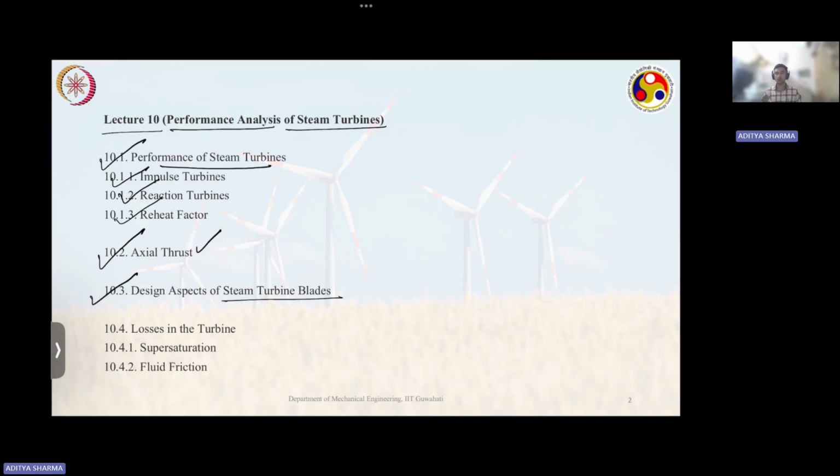But if you see the whole blade from the axis of rotation, omega is the same for the whole blade, but the radius changes as we move towards the tip of the blade, which eventually changes the blade velocity. All these things need to be considered while we are designing our blades.